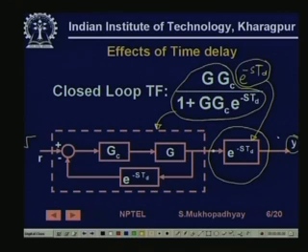On the other hand, apart from the delay, how is this plant different from the delay free plant with which we can do ordinary feedback control? Firstly, there is a delay caused in the output. Now, this delay cannot be avoided, but nevertheless it is not going to cause any problem in stability. Simply the response will be delayed by an amount TD, which cannot be helped.